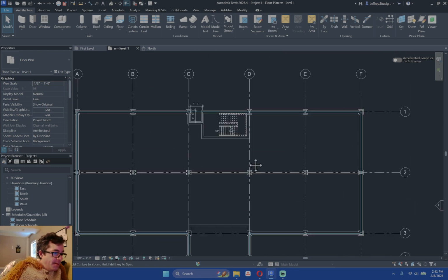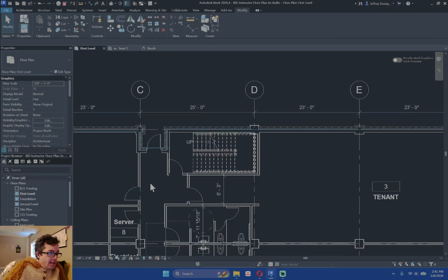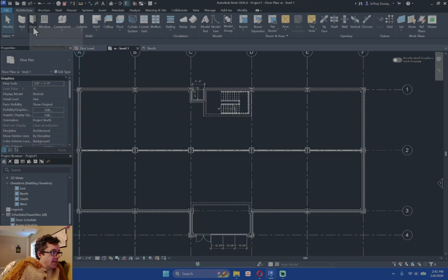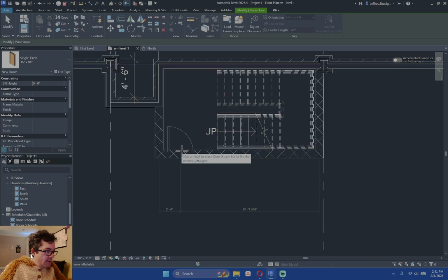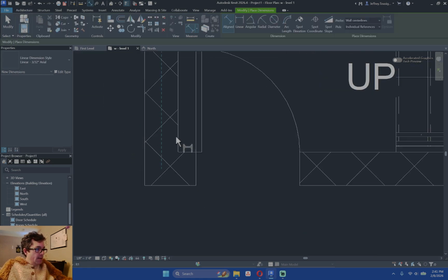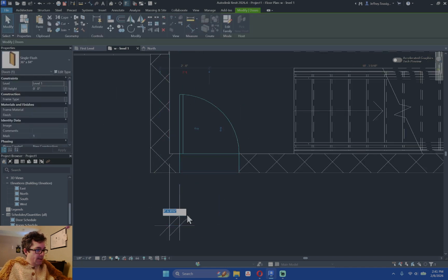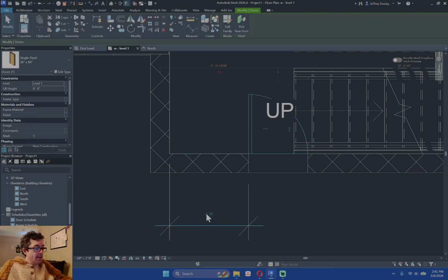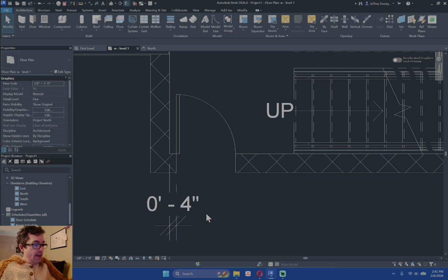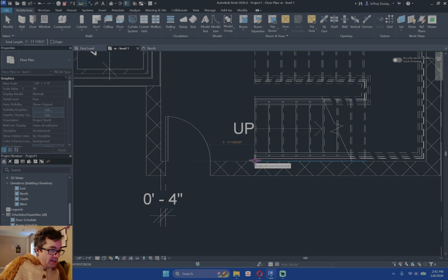So this stair is big enough. I'm not even going to propose this stair out because I'm fairly confident that this stair up here is going to work just fine. Because it's proposing, yeah, the entry is going to be here. So that gives us, if we big door it, and we give the door a generous 4 inches. Yay. Awesome. That gives us from the door to the face of the stairs just a hair short of 3 feet. So that'll be great.